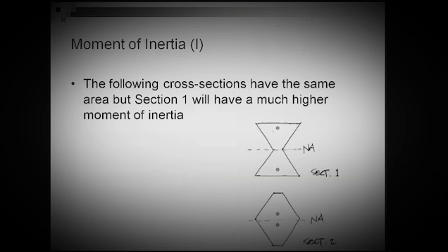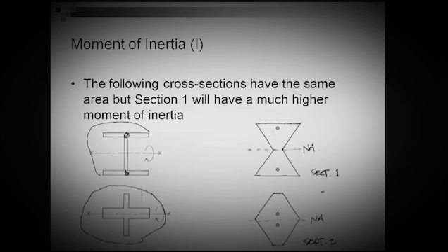So it makes sense. That's why in steel sections, we tend to use an I-beam, a beam that is oriented like such. You would have the center of that mass further away from the neutral axis, so we can get the most efficient beam. The same beam, if I were to use the exact same area, same dimensions, if I were to have it in a double T section like that, almost a plus sign section, it's terrible for deflection and it's terrible for resisting bending moment.